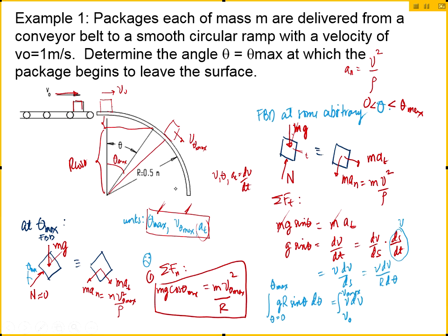And if we learned anything from the first week, we had 3 kinetic principles, right? Newton's second law directly relates forces with acceleration. Work energy relates what? Speed and position with forces, right? And theta is a position. Therefore, if you want a relationship between theta and v, work energy is a more direct way of finding those.